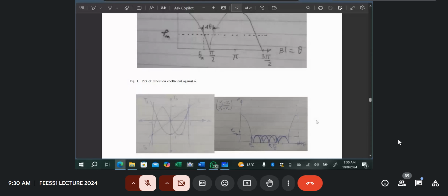You can have a two-section, show us the plot. You can have the three sections, show us the plot. And how do you calculate the impedances? Maybe Z1, Z2. How do you calculate the fractional bandwidth? How do you calculate theta M? You can see theta M in the diagram here. It's important for us to show how that is calculated from equations. Again, remember, as I said, in the fifth year, you use the results of the theory to do something that is practical. So you just need to show us those equations on what we normally call the polynomial coefficients.